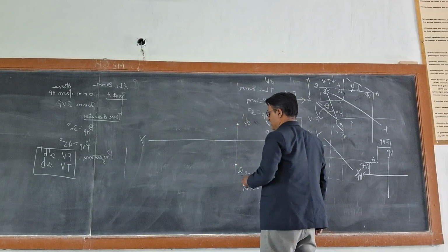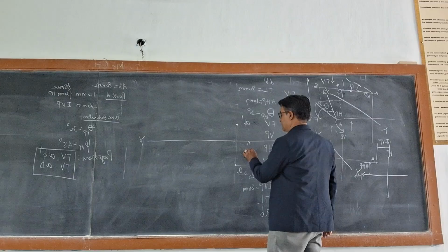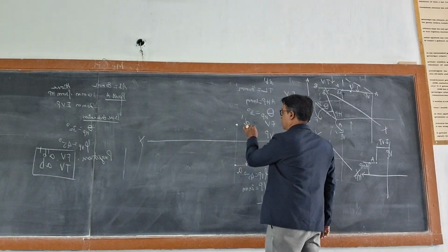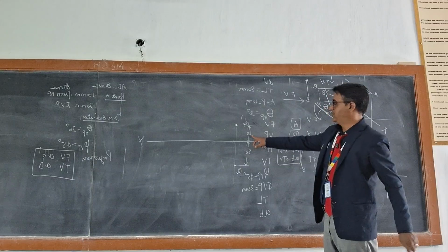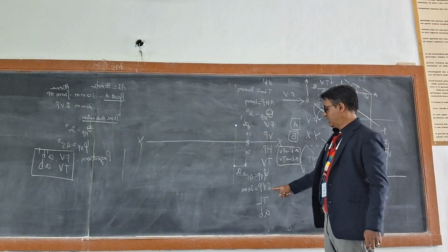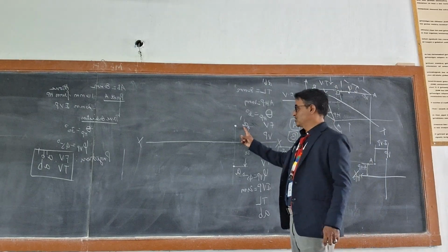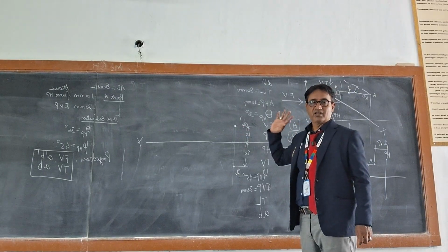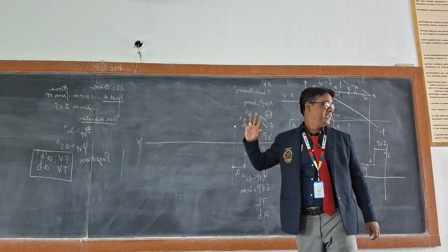Now after drawing this, you have to mark the dimensions. So what are the dimensions here? It is 20 and here it is 10. See, AHP is 10 mm, above XY as per the format, and IVP is 20 mm, below XY as per the format. Now you have drawn the projection of A. What you have to find out now is the projection of point B.